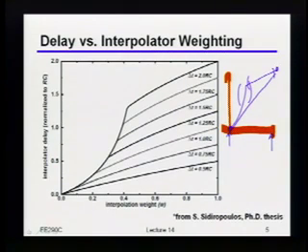So what this is basically saying is that you really want to avoid this kind of behavior, because what you really want is something to look linear, not because necessarily you care about the linearity in and of itself, but you just want to make sure the step sizes are as small as they can be. Okay? If I'm always covering the same two endpoints, the only way to make the worst case step size as small as it can be is to make it linear. Okay? So now, out of these curves that we're showing you here, what does that say are the curves that you think are good? 0.5, 0.7. Yeah, it's these two down here, right?